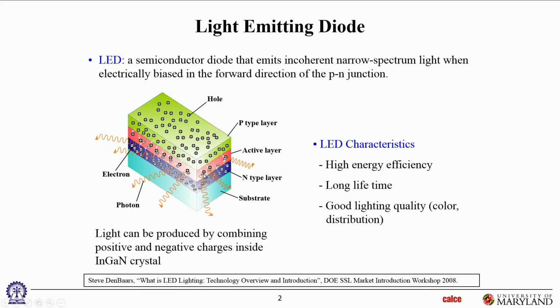I'm skipping over the halogen lamps. They're also in that family of lamps. LED lamps last much, much longer. They're designed to actually last about 50,000 hours, okay? That's because intrinsically, these are very stable devices. They don't degrade very easily. What dies is the packaging, not the device. The device is very stable. So in all the accelerated testing that we do for LED devices, we're never able to fail the device. We fail the packaging. All the degradation modes we see are in the packaging.